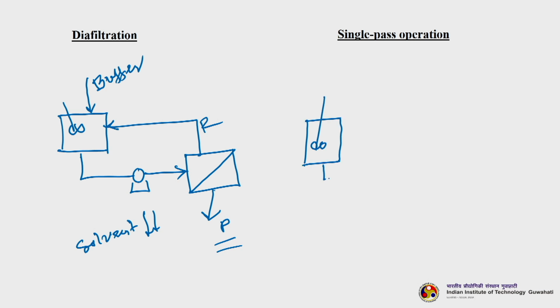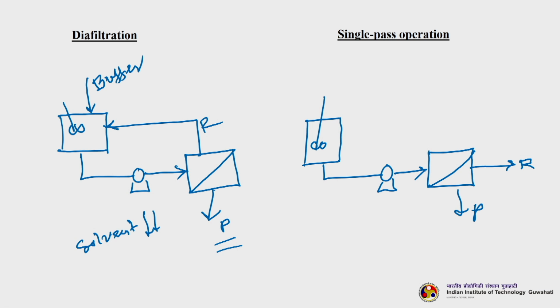It is a feed tank. Okay. So, there is a pump which is getting feed to the cross flow system. So, it is retentate and you get permeate. Now, this is a typical single pass system. Now, what is happening in this? Now, try to understand that in a single pass system we cannot achieve the targeted separation, and they are not common also in industrial parlance, because they require very high feed flow rates. Okay. So, single pass cannot achieve the desired separation.